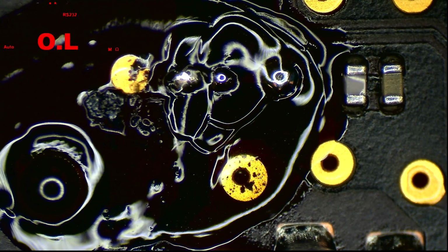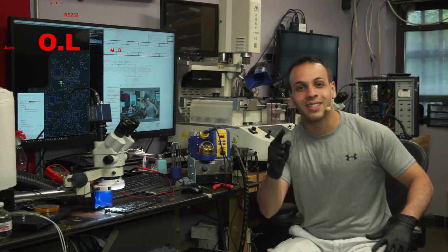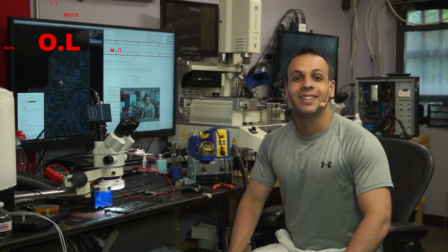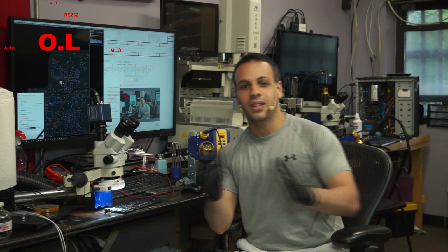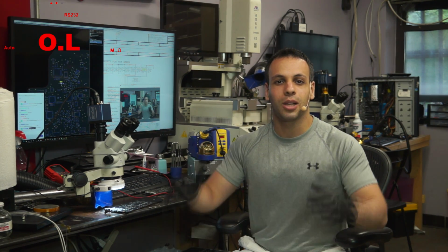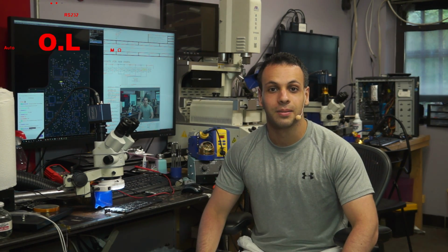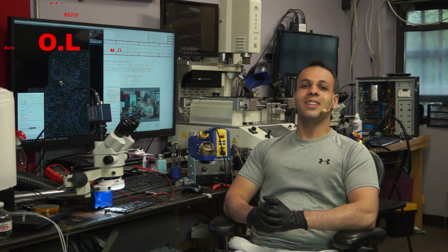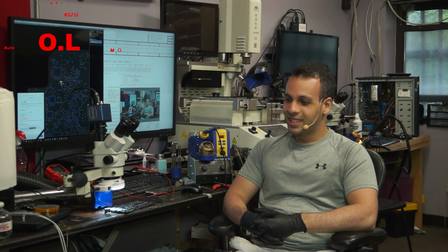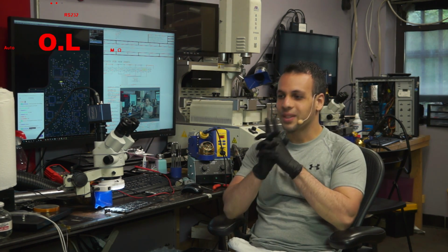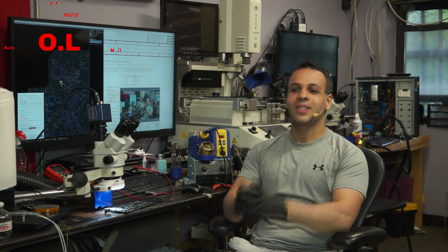And you know what the funny thing is? Of all the shit that we checked, we didn't check that. I checked the resistors in between the LCD driver and the LCD connector, but I never checked the pull-up resistors or their resistance to ground. What a noob mistake! That is so incredibly noobish. Oh, that's fucking embarrassing.